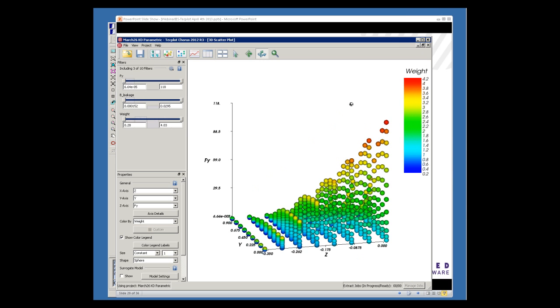Here we're going to go into Tecplot Chorus. Now you're looking at two of our variables, y and z, and force is on that z-axis. But we've got the capability to begin to interrogate that data versus those three key parameters. I can filter it, for example. I can go to the force and say, look, I only want values of force that exceed a certain level. So I'll begin to pick up this filter on a force value. As I do that, you see that some of the data images begin to disappear.